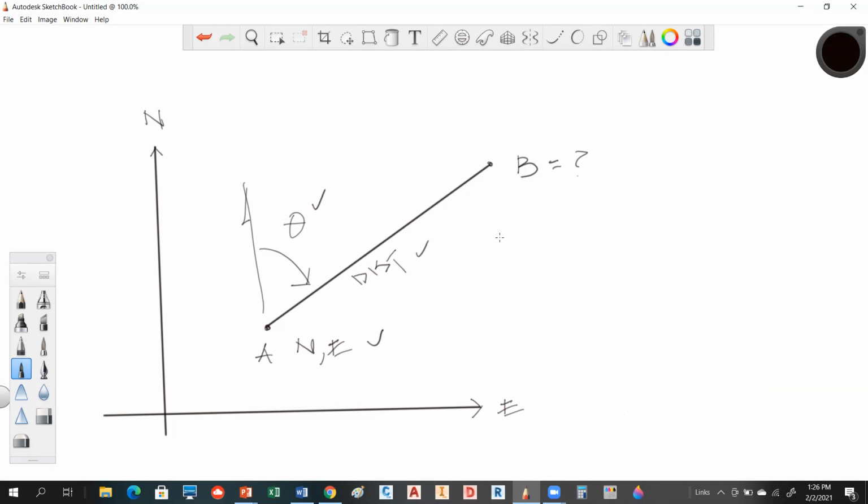What that basically said was you can take the northing of B is going to be equal to the northing at A plus the latitude A to B. That should look familiar because we used it last week. And then the easting of B will be the easting of A plus the departure A to B. And we're going to use this when we get into the side shot concepts. So we're going to see that quite a bit.